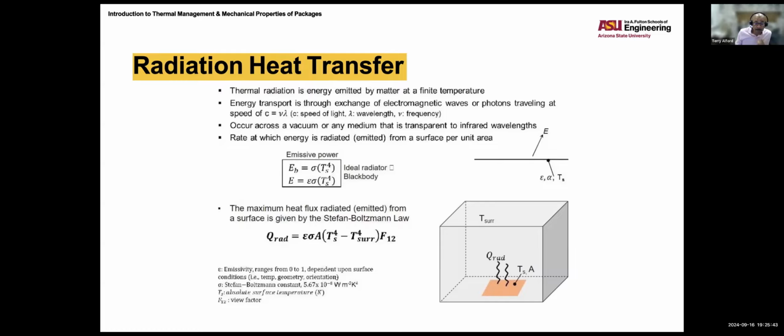In this case, they are looking at natural convection, and based on this standard, you can go and look it up as well. You want to make sure you have the correct fixtures, that means materials, measurements, and placement of the package, so that you can have a valid measurement. Have the correct test board, that means the correct number of metal layers and the package type.